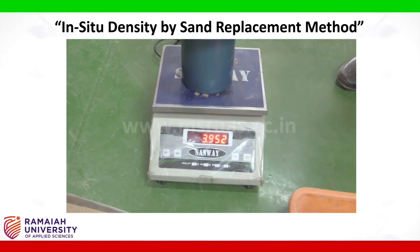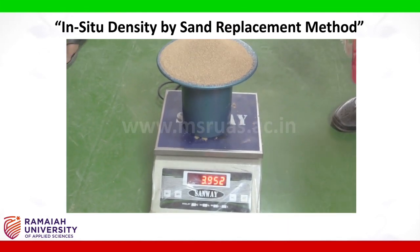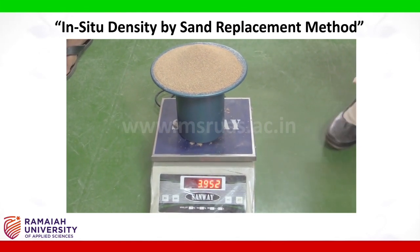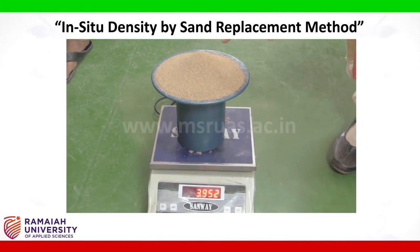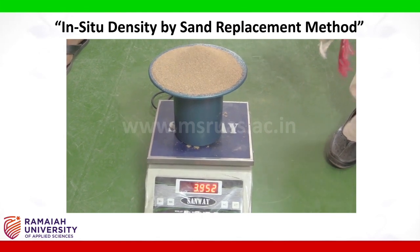This weight includes the weight which is filling the container as well as the conical portion. Now to find out the amount of sand which is filling only the calibrating container, we have to deduct the weight of the sand which is filling this conical portion.